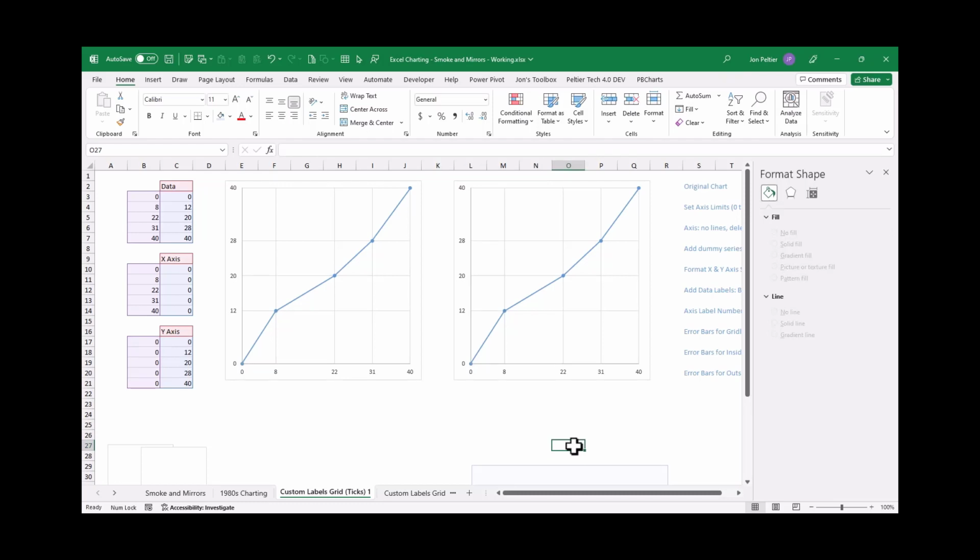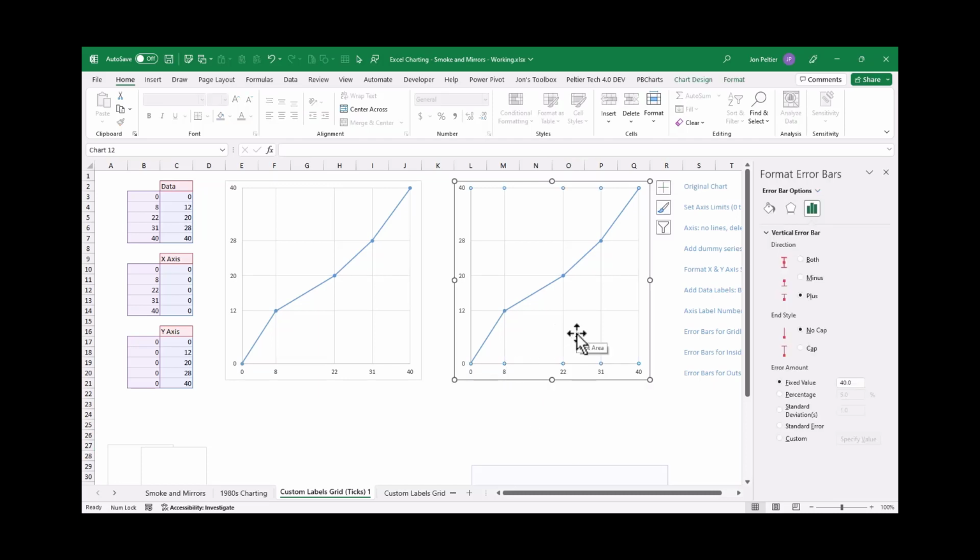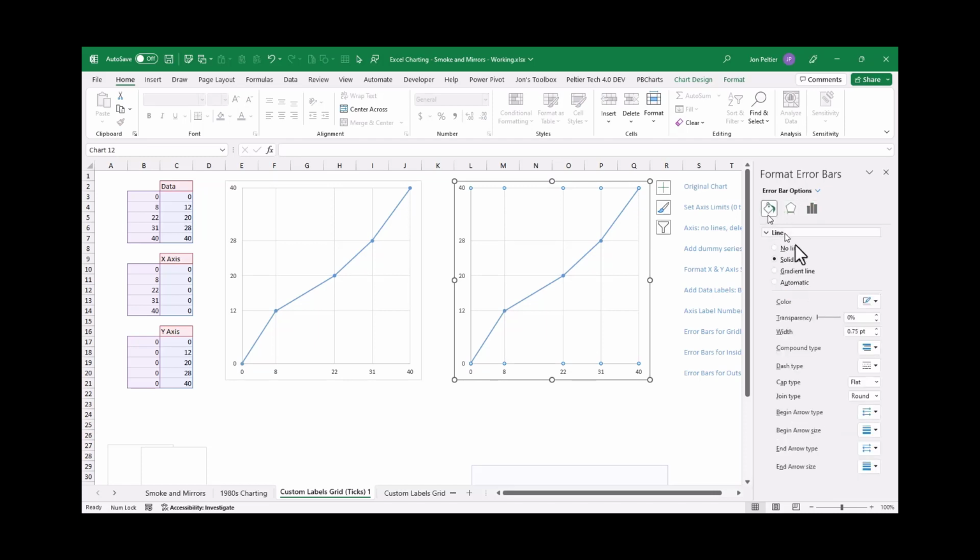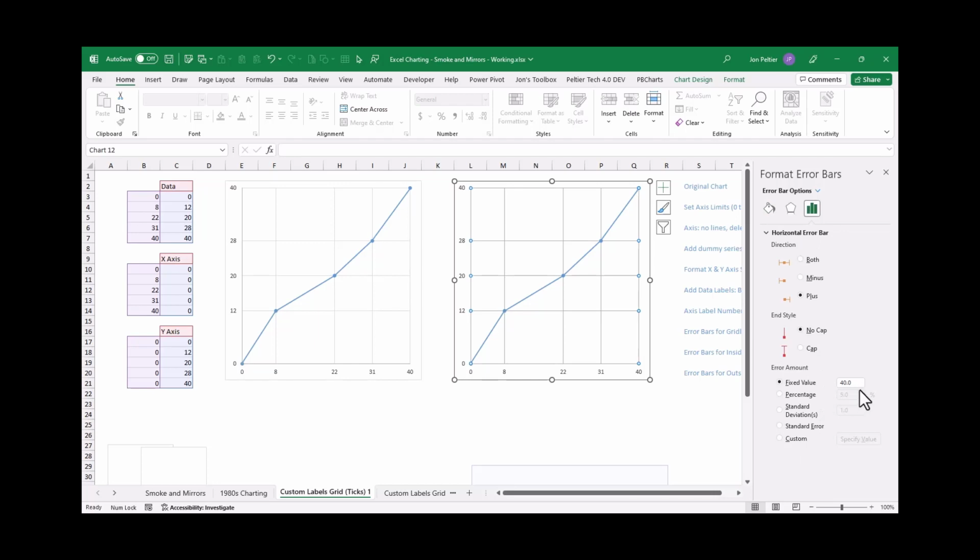Now, suppose I did want short inside tick marks for those positions. What I can do is I'll take these and I'll format the color to make them as dark as the axis. And I'll do this first because once I make them shorter, it's harder to select them. And I'll select that one and I'll say F4. And now, what's a good length for a tick mark?